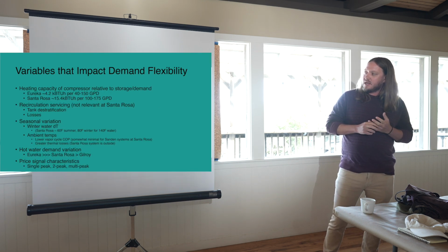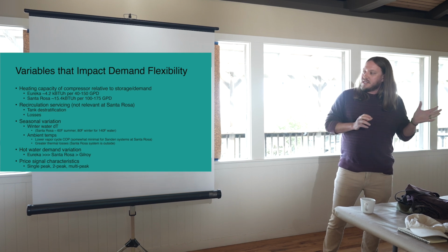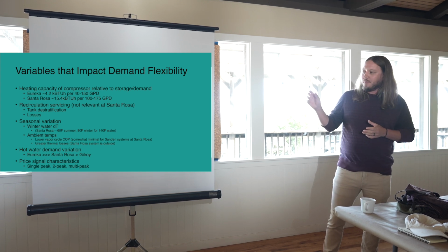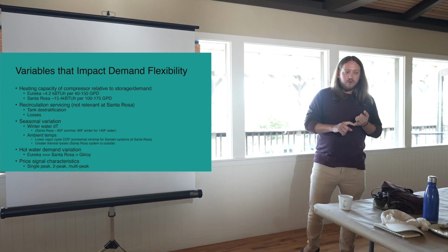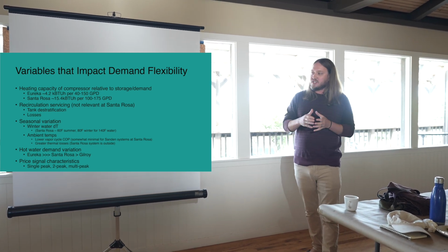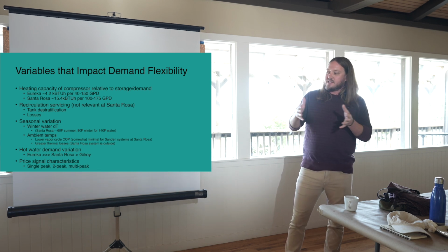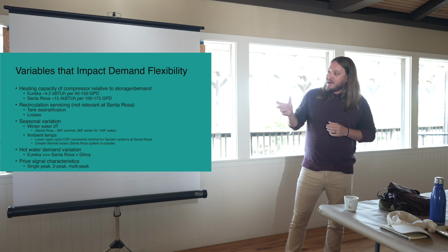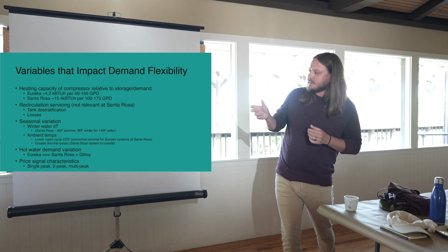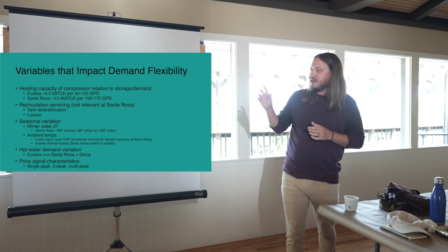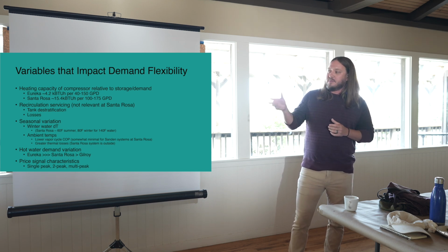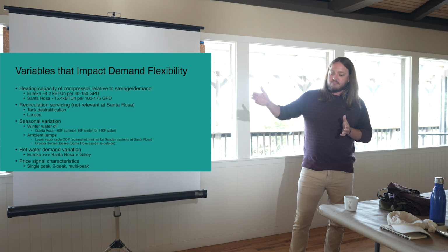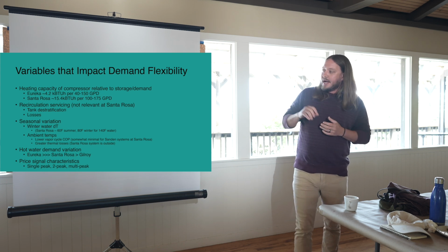Next slide, please. All right, so Evan touched on a bunch of these, but outside of people, we have a bunch of other things we've got to account for. The heating capacity of the compressor relative to storage and demand, right? So how long is that recharge time? That impacts how much we can squish into a certain period or shift around. Eureka, for instance, has about 25% of the heating capacity, but with roughly the same amount of demand, right? So it takes much longer at Eureka to do the same amount of work, essentially.